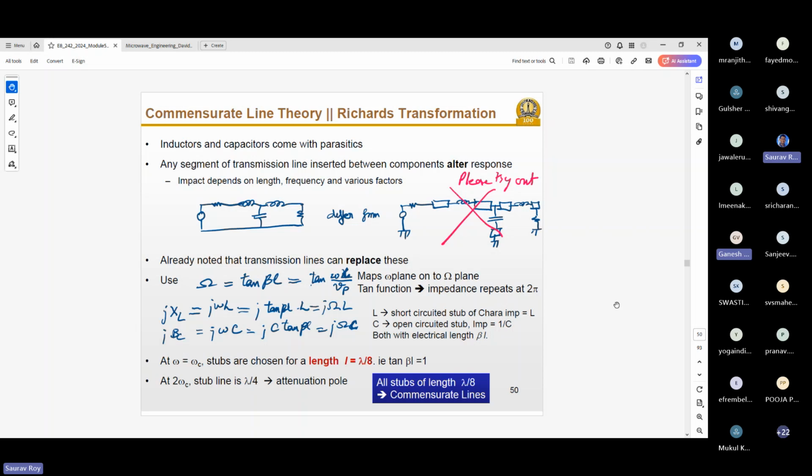I have one more question. Whether self-resonant frequency will come into the picture based on the component, where at a certain frequency it acts as an inductor and after that it becomes a capacitance. See, all these effects will come obviously, but those are non-ideal effects. So initially, first we will take the ideal components, and then we will go towards the lossy components. But ideally, it behaves very well. You can actually make a short circuit and open circuit in ADS and design it, and you will see that it behaves like a capacitor and inductor. You will get input impedance similar to a capacitor and inductor.